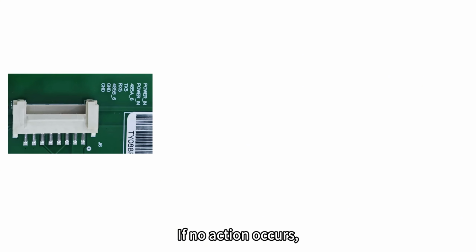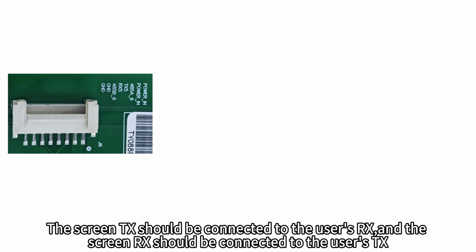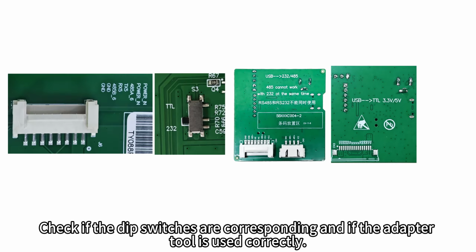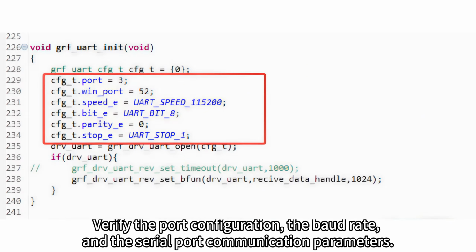If no action occurs, first check whether the hardware connection is correct. The screen TX should be connected to the user's RX, and the screen RX should be connected to the user's TX. Some products have TTL to 3 DIP switches. Check if the DIP switches are corresponding and if the adapter tool is used correctly. Verify the port configuration, the baud rate, and the serial port communication parameters.